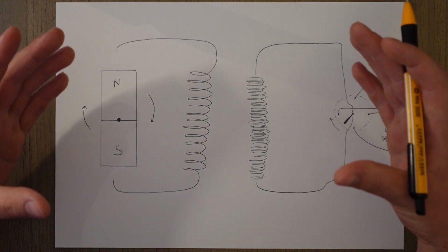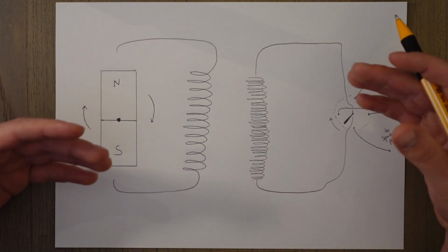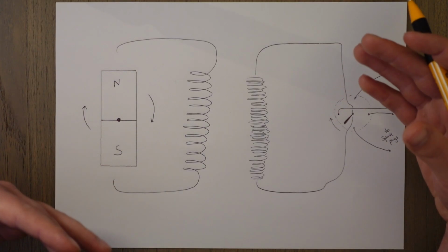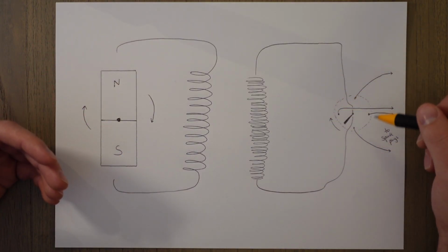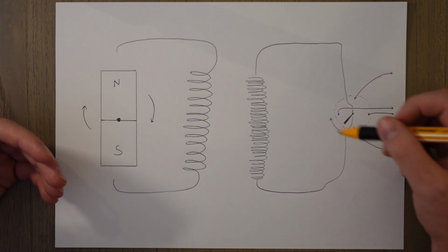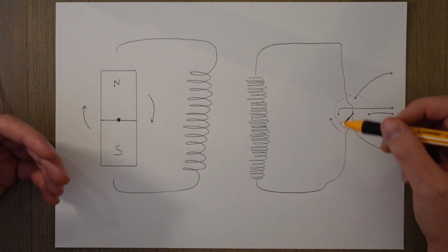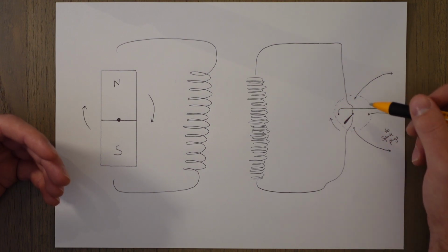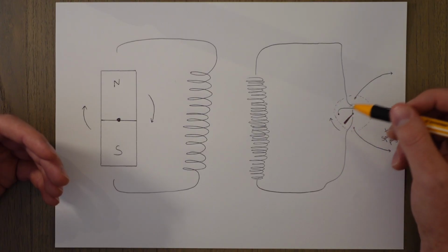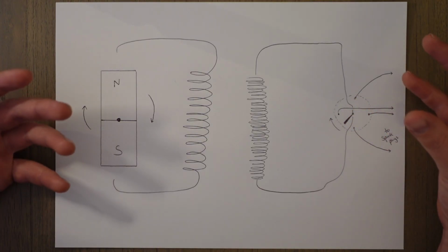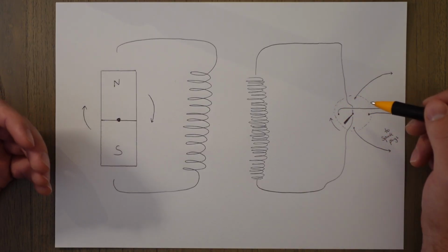We would not want to have one of these magnetos for every single spark plug, because it would also lead to the potential for failure of those systems. So what we can do is use something called a distributor. A distributor is essentially a spinning switch. The distributor spins round, making and breaking the circuits with all these spark plugs, and does it in the correct timing and the correct order in order to make these circuits send the electrical signal to create the spark and then move on to the next one, and so on in this cyclical fashion.